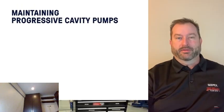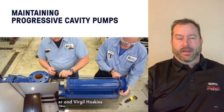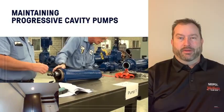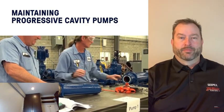Okay, the next area we wanted to talk about is maintaining progressive cavity pumps. A lot of people want to know, are these pumps difficult to repair in the field? They can be. Some of the larger pumps have extremely long stators, so they can be pretty heavy. Also, you have to allow for enough room on the discharge side of the pump to remove that stator off the end of the rotor.